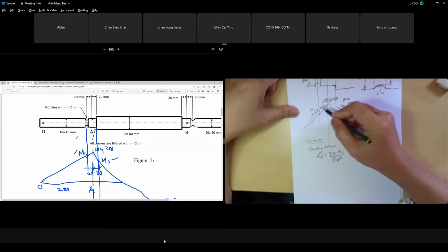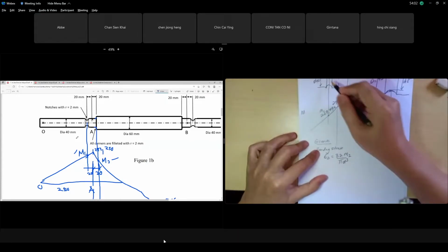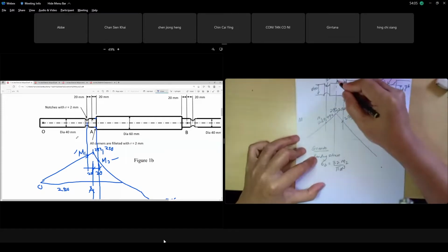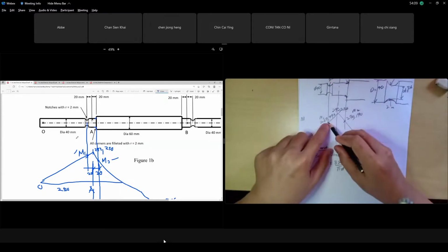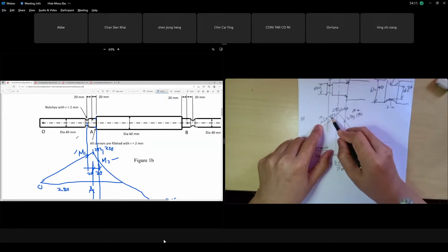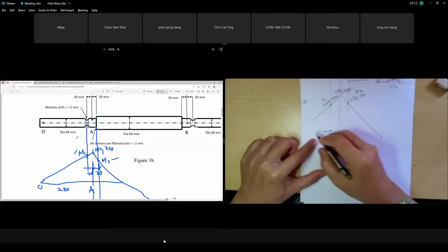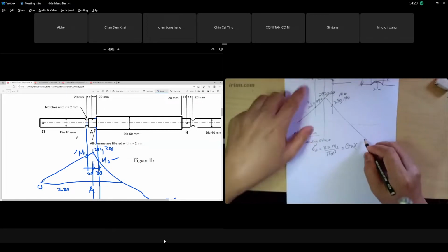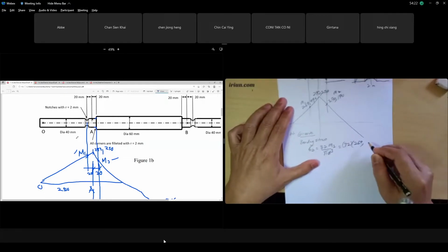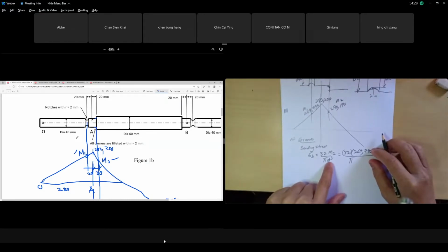So for our moment at the groove here, bending stress at the groove, because we have a moment, we do not use the moment at A, 293,250. We use moment 1, which we solved by theorem, and got 269,790. So your bending stress at the groove is 32 times your moment 1, 269,790, over pi, which diameter? Diameter cubed. Which diameter, guys?